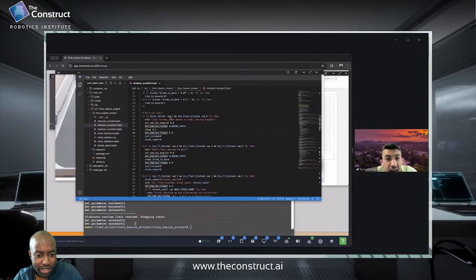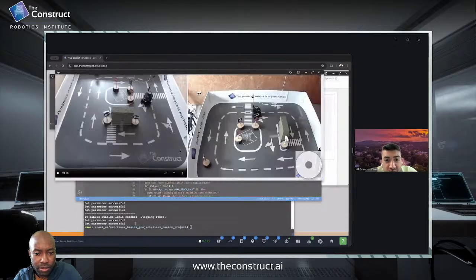How do you avoid that? I have it here. This one is just turn. If the robot just turned, and if the front is not blocked, it says just turn and let's move forward. So I set the command velocity of linear to just go in that direction. If we don't have this one, I figured that if we start the robot from some points that go directly from here, where the front of the robot is in these directions, then it's just going to turn around a lot about itself.